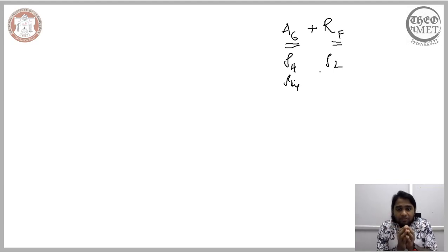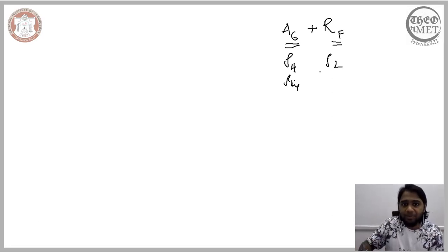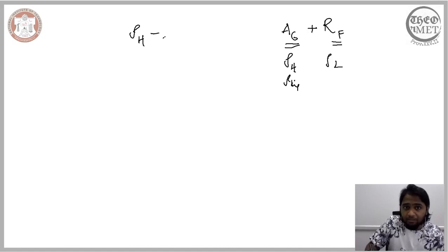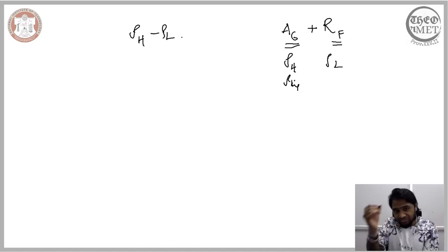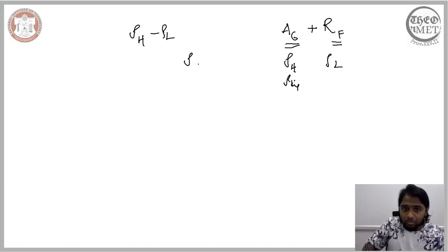So therefore, when we say the behavior of a particle in a medium during gravity separation is the combination of accelerating and resistive force, what essentially we are talking about is the difference between the density of the heavier particle minus the density of the medium, and similar to that, the density of the lighter particle in relation to the density of the fluid. So the behavior of the heavier particle in a given medium is influenced by this term here.